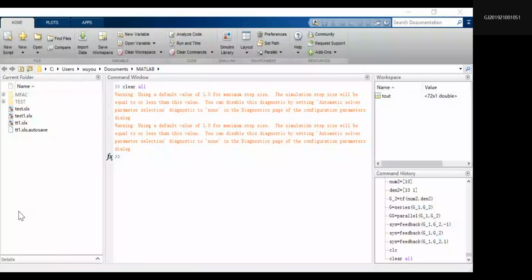The output curve responds immediately at the simulation start point. So step time is the time you set for when the step happens. Remember? Clear? And here we have the final value. If it is not a unit step, you can change it to whatever value.